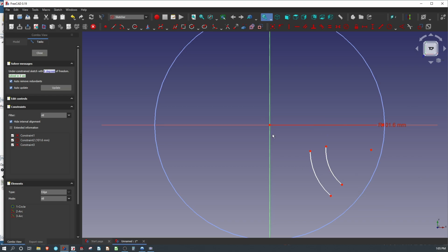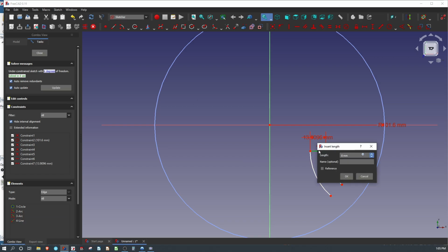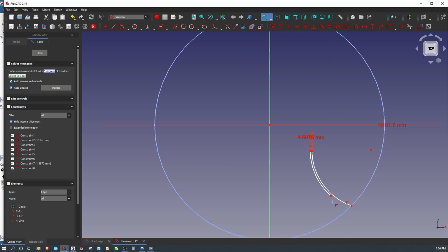Again, this is not a beginner's tutorial, so any good designer really ought to know multiple units and be comfortable using them. We're going to say H for horizontal, Shift H, 0.0625 times 25.4. And we'll grab coincident here. Coincident these. Just as before, as you can tell, the sketching environment feels almost identical, as it should. 6.35.